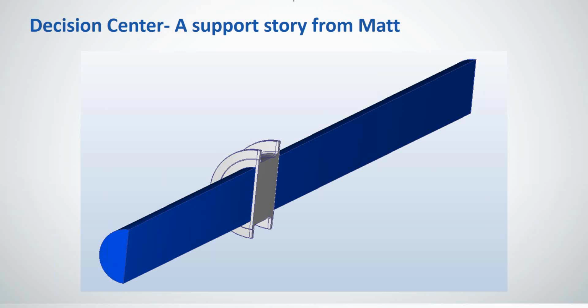So this was a model where I basically used both an XY plot, and I just used my approach of having an inlet and outlet summary plane, and just kept trying things and incrementally improving my pressure drop.